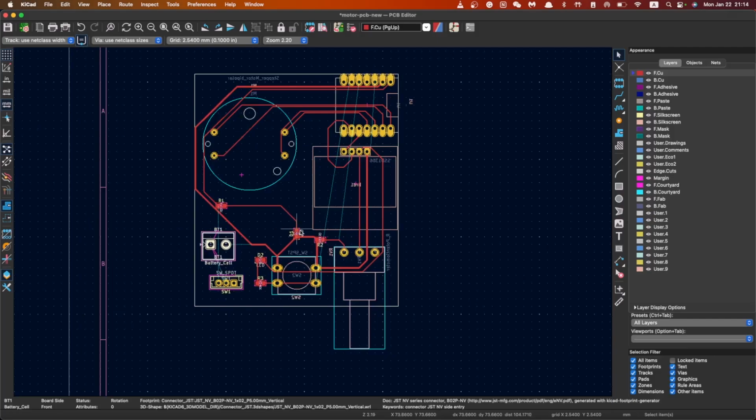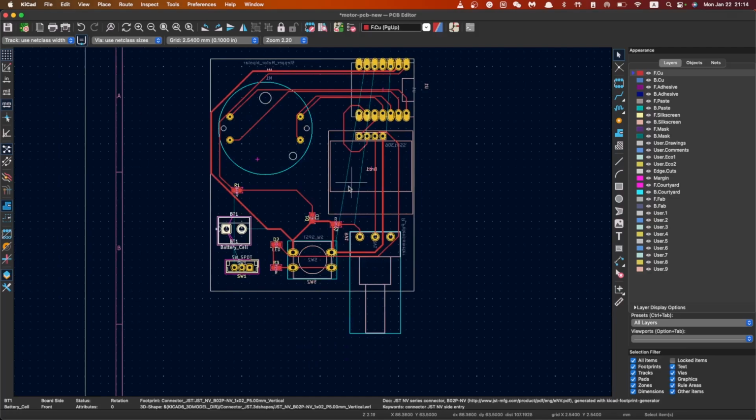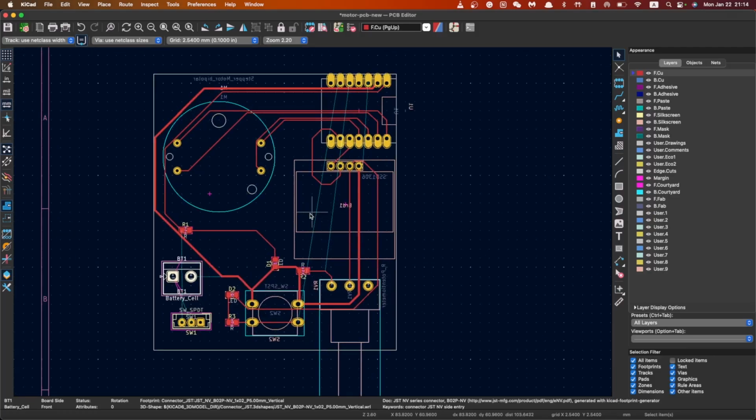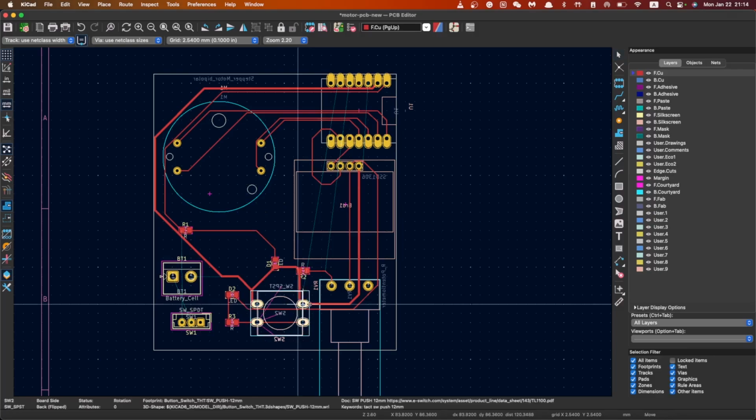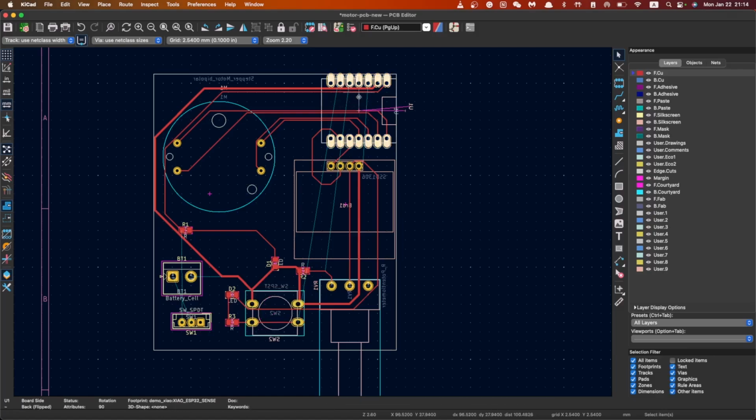So what I want to do right now is to rearrange this PCB board, because as you can see here, we've got a problem from the end of last video, which is that the button here, those pins to be connected to the microcontroller, is on the other side of it and we cannot reach it, because it's pretty obvious that these wires or tracks here are blocking it from being connected.